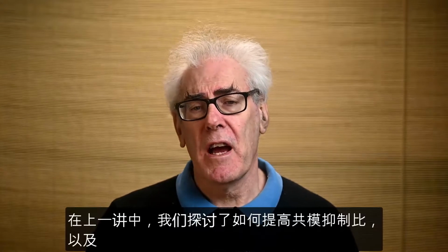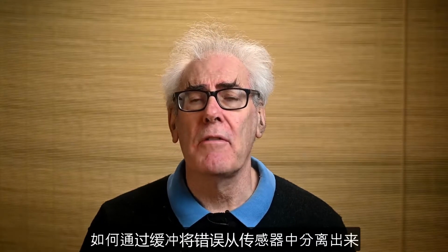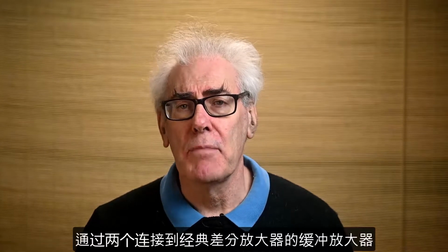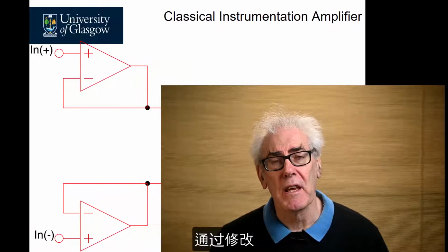In the first lecture on instrumentation amplifiers, we looked at how you analyze them and the improvements in them. In the last lecture, we looked at how you can improve common mode rejection ratio, and how to analyze it by improving the matching resistors. We also looked at how you can separate any errors from the sensor by buffering it via two buffer amplifiers connected to a classical differential amplifier.